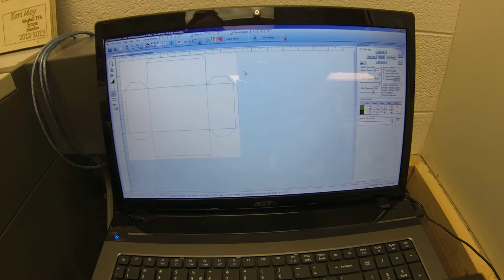It's going to default bring it into what is called raster engrave. We want to click on vector cut. A vector is a line that can be edited, and it also can be assigned a toolpath and cut. Our raster is something where it would come out in engrave or do an etching of. We're not going to do an engrave just yet. That'll be in our keychain project. So we're going to hit vector cut.